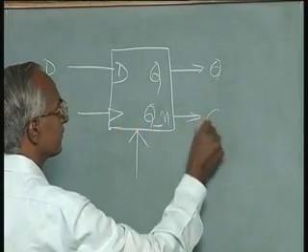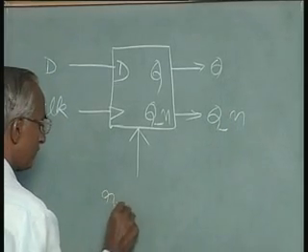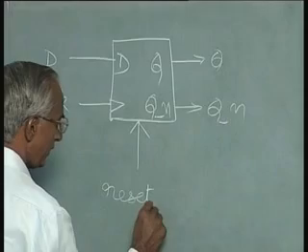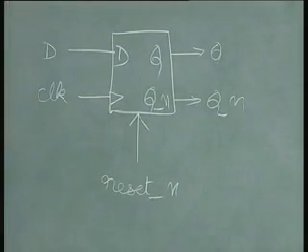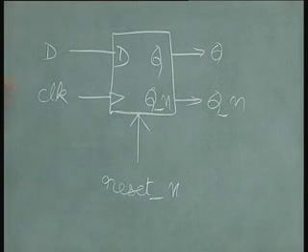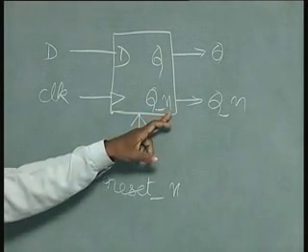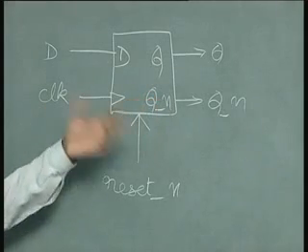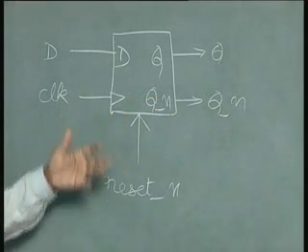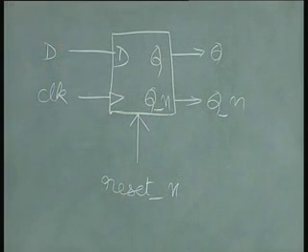It is the same as such. Further, we will have one active low input called the reset. When a reset is applied, the flip-flop is cleared. That is to say, Q becomes 0 and Q negative, where N stands for negative, but you can regard it as low. Designers use this as active low, and this is, I think, more popular.